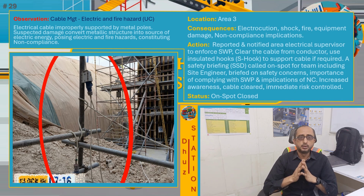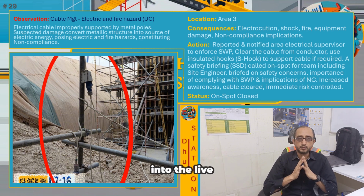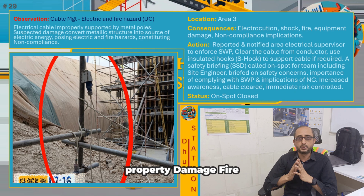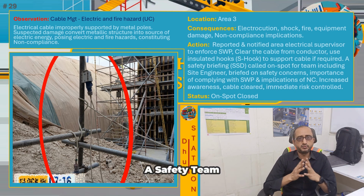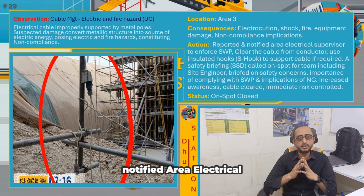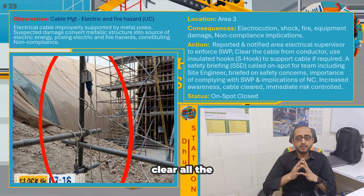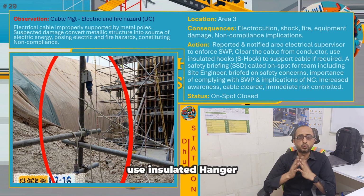Location is area 3. Consequences: in case of any damage, the whole structure will convert into a live source of electric energy, may lead to electrocution, electric shock, property damage, fire, and implications of a non-compliance. Action taken: a safety team reported the issue, notified the area electrical supervisor to enforce the safer procedures effectively, clear all the cables from the metallic structures, use insulated hangers or hooks.